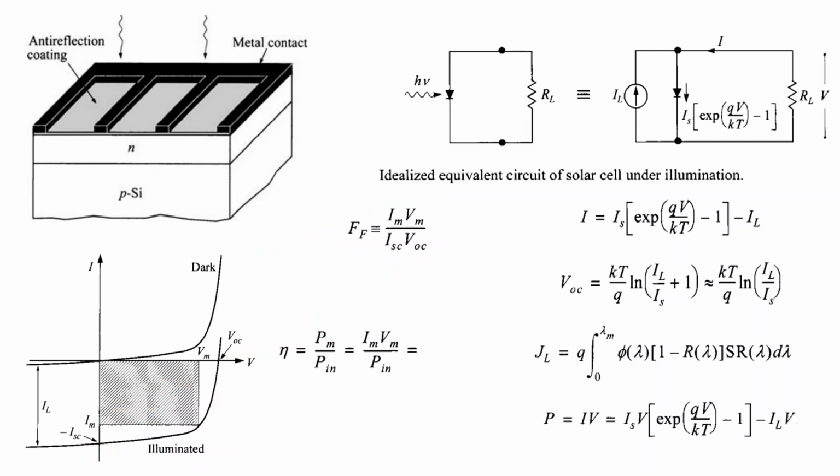most publicly interesting parameter, which is efficiency. So we have maximum power, which we can extract from the solar cell, and input power. Input power is integrated over this spectral distribution of solar light. So that is 1000 watt per meter square under AM 1.5. And maximum power is defined as the product of maximum current and maximum voltage.